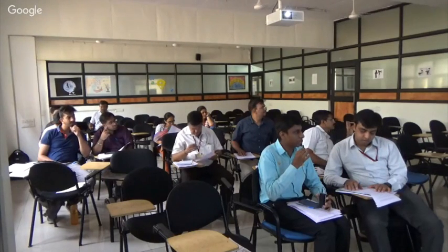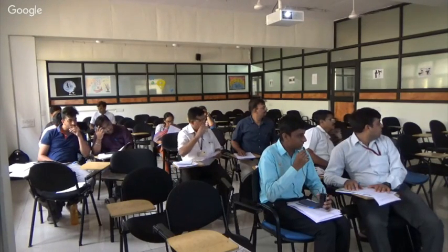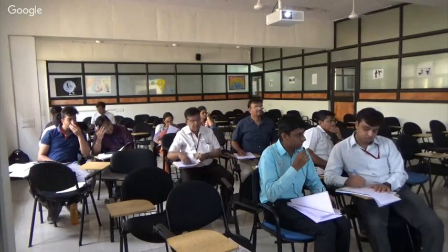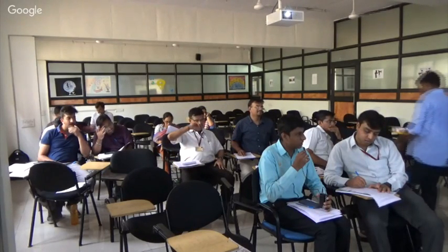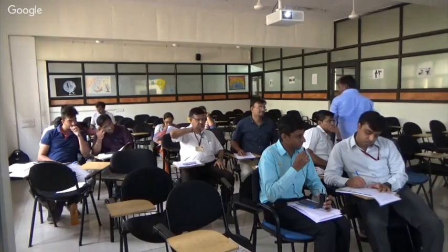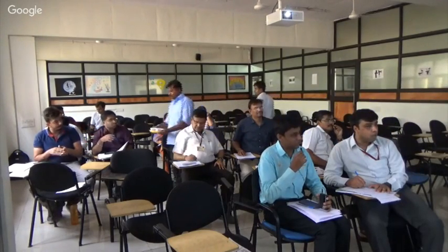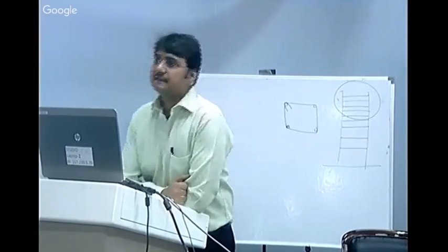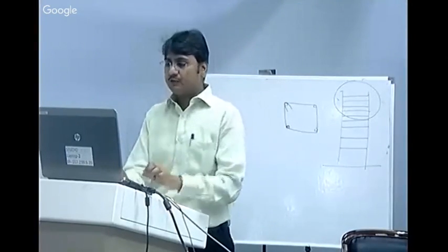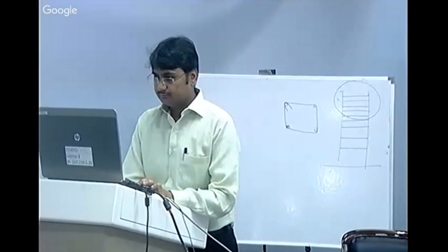Distance of opening from the corner should not be less than 600 mm. As I told you in the earlier lecture also, it should not be less than 600 mm. So the data which are not given, you need to consider. The distance from the corner should not be less than 600 mm. That is Codal provision. Okay, thank you, sir.